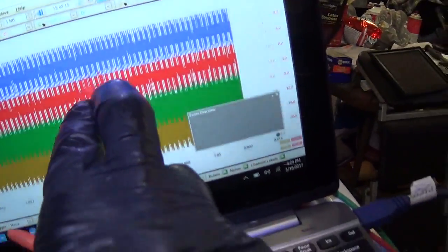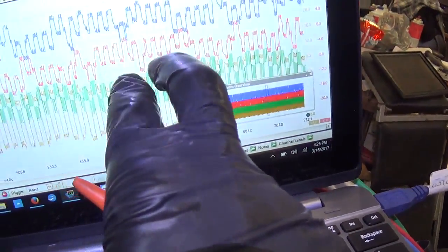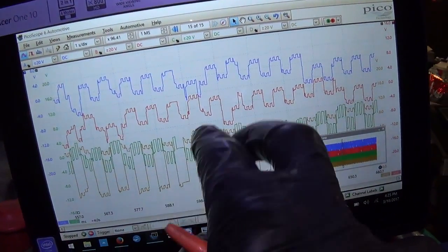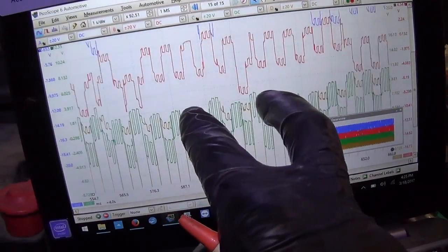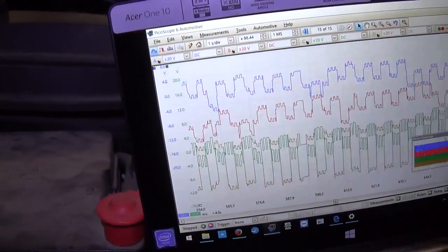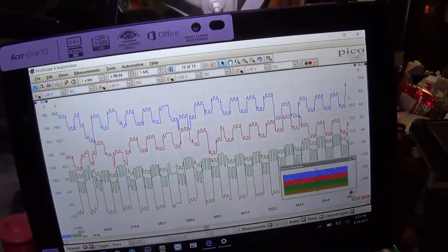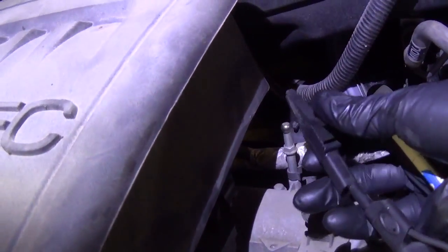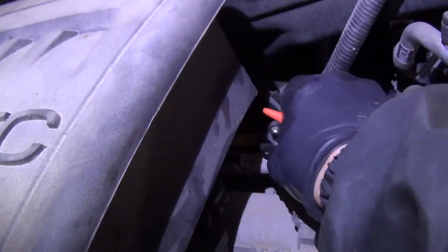We can stop that capture. Shut it off. So this is where the touch screen comes in handy. You can just zoom right in. And what do we see here? That is some funky stuff. Question is, is our ground good for our scope? That stud might not be a good ground. So let's relocate. Oh, see, my alligator clip wasn't even plugged in. Let's try that again.